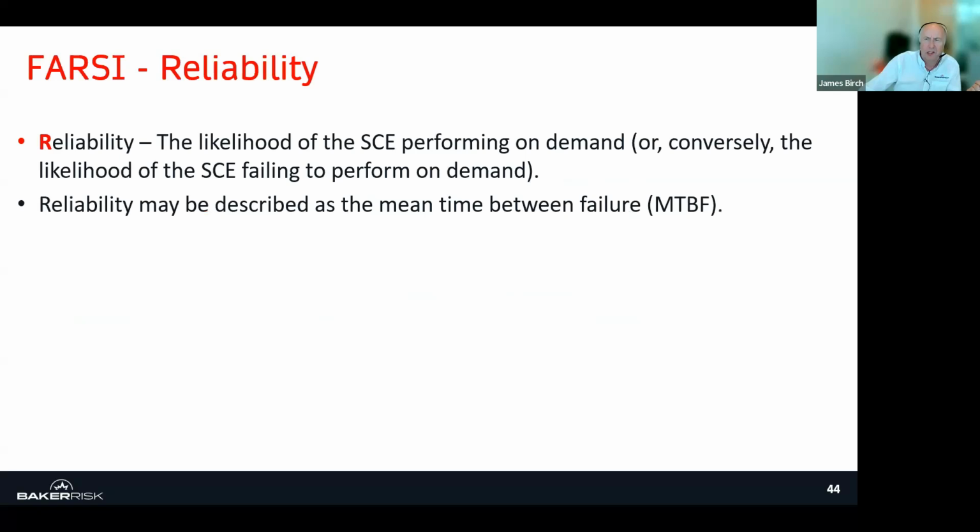The next consideration I might have is, how reliable are they going to be? The manufacturer tells me that they will always work. Probably not that good in reality. Maybe I get 90%. So I now have another set of criteria that say 90% of these units must work for 90 minutes at the required lighting level when they're called upon to perform. So it's starting to give quite a lot of definition on each of these elements.